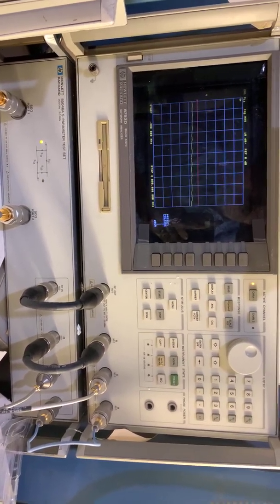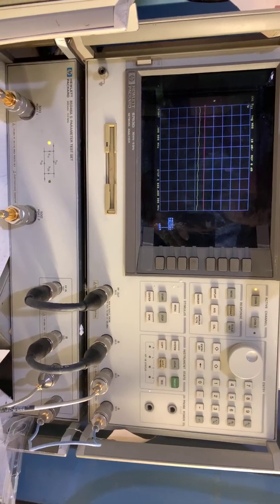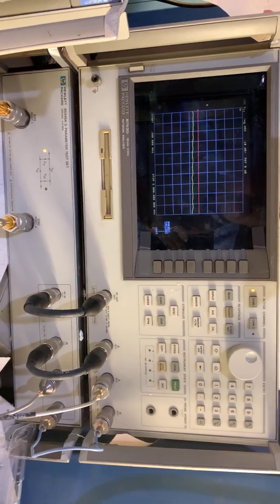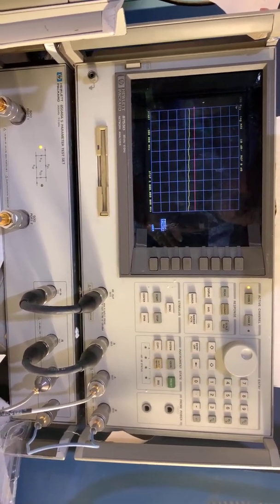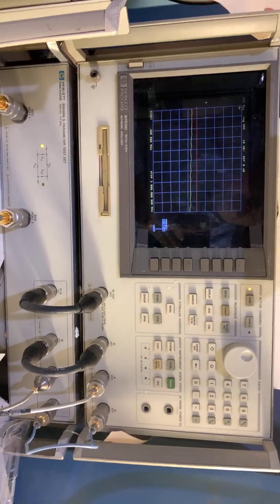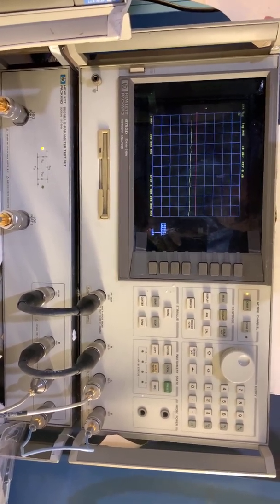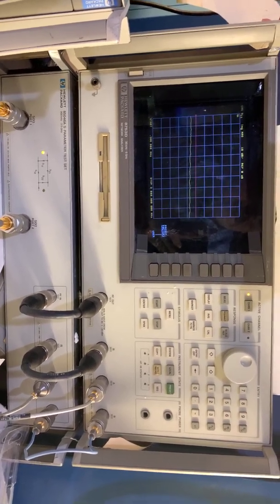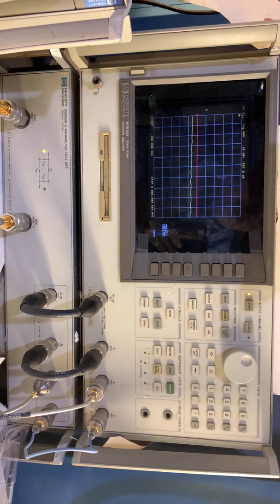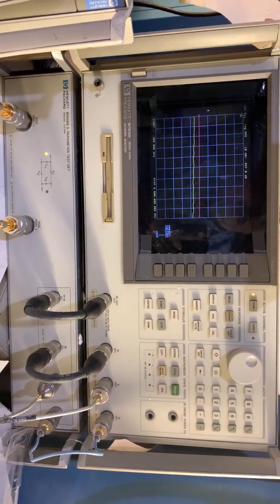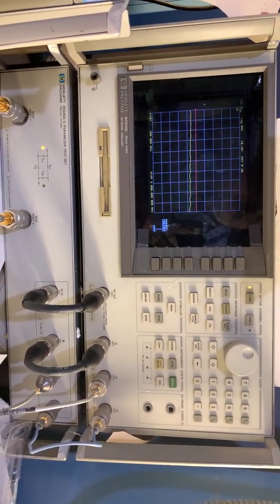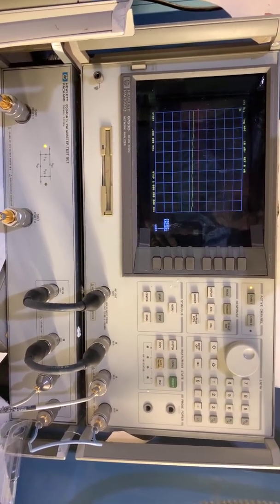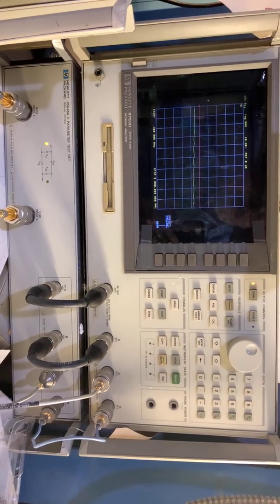So what we are using nowadays are commonly referred to as vector network analyzers or VNAs. The word vector already implies that those network analyzers are capable of measuring phase as well as magnitude, as opposed to older scalar network analyzer systems that are hardly used anymore nowadays. They used diode detectors, and they were only capable of measuring magnitude and return loss, but no phase relationships.